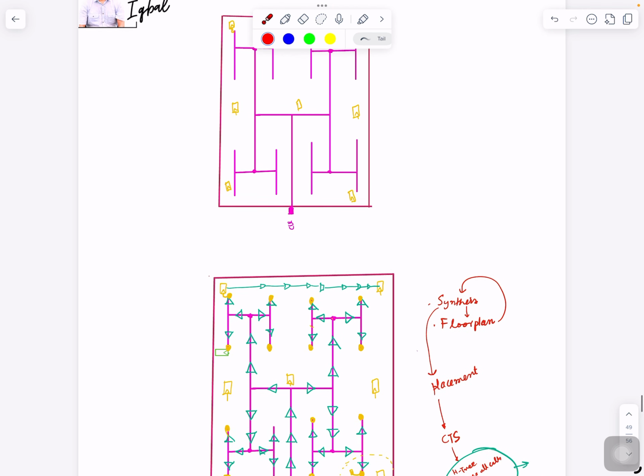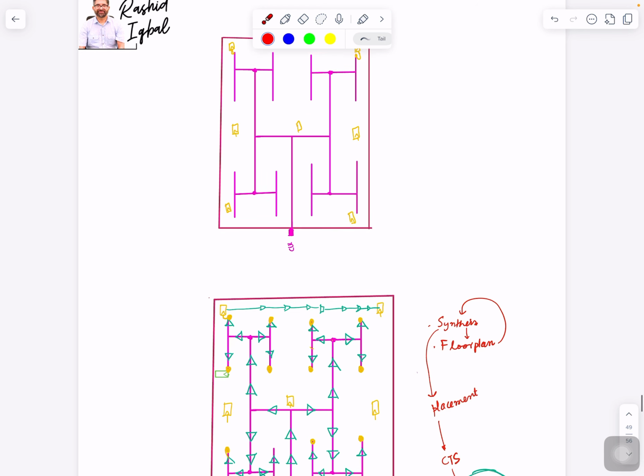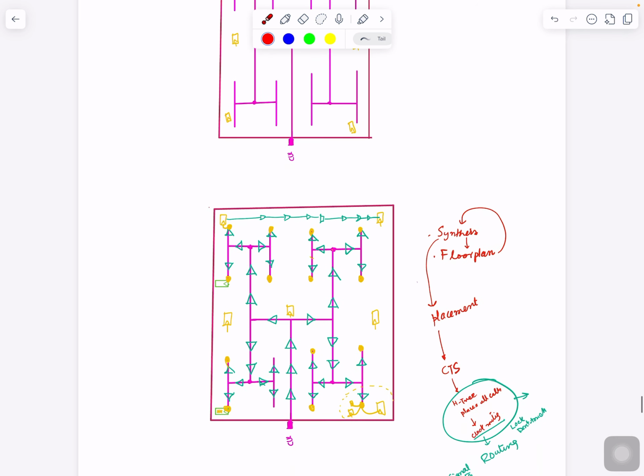Okay, and this is called H tree because of the shape of H these routes are making. And when you want to put those buffers, you want to put them starting from here, 1, 2, 3, 4, 5, 6, 7, 8. This flop is saying 8. So even this flop should see 8. I don't know if we have 8, 1, 2, 3, 4, 5, 6, 7, 8.